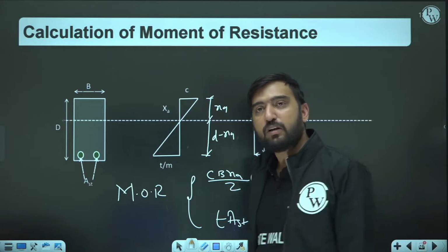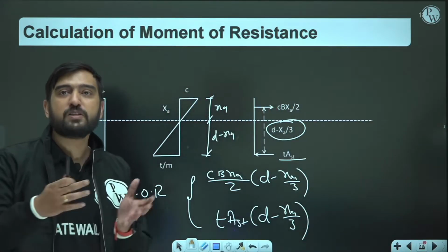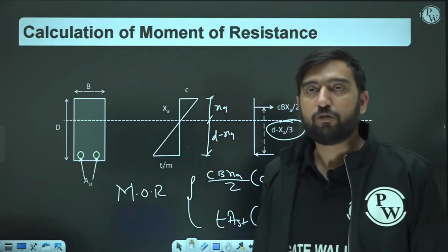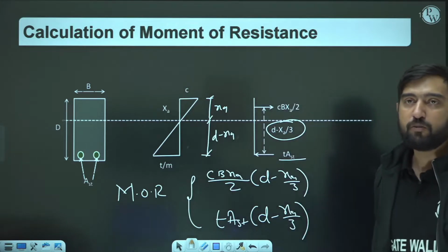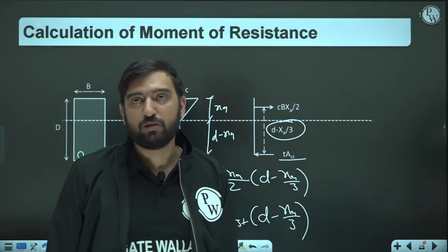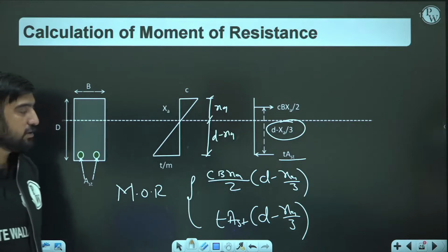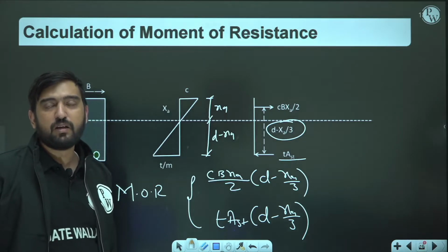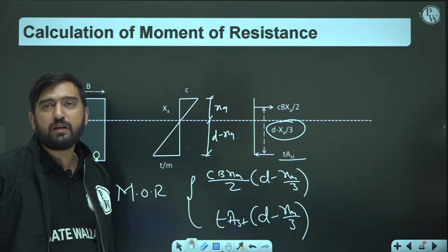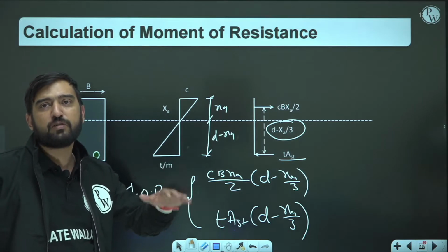Similarly, in an under reinforced section, if you want to calculate the moment of resistance from the compression side, then again you need to apply similar triangles in the stress diagram, and from there calculate the developed value of stress in concrete, the C value. So all these three possibilities can be there. Theoretically, for designing we take the critical or balanced section as the benchmark, although in practice we give our section slightly on the under reinforced side.